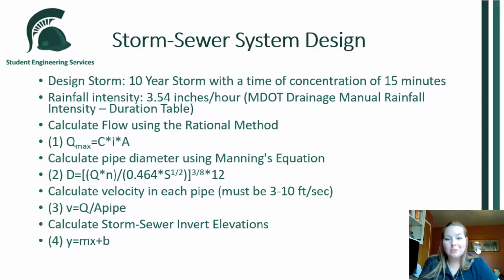Calculations made for the storm sewer system design were done using the following methodology. The design storm is going to be a 10-year design storm with a time of concentration of 15 minutes, and the rainfall intensity was determined by the MDOT Drainage Manual Rainfall Intensity Duration Table.